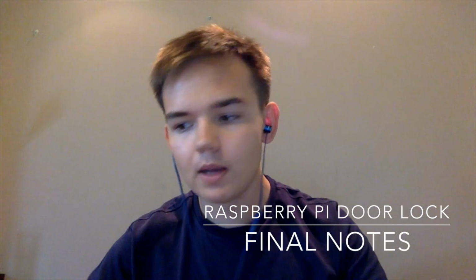Just a few quick final notes for the video. Dependencies: there are some dependencies for some of the programs. They'll be in the description. IP addresses: you will most probably have a different IP address for your Raspberry Pi. You will need to change the programs to accommodate for that, the socket programs in particular.